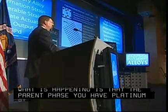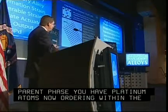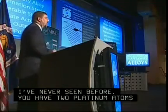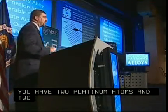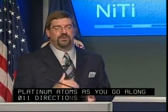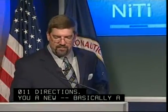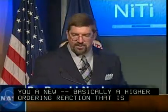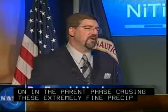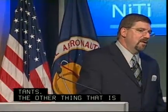doing it in a way that I've never seen before. You actually have 2 platinum atoms, then 2 nickel atoms, then 2 platinum atoms as you go along 011 directions in that particular plane. So you have basically a higher ordering reaction that's going on in the parent phase, causing these extremely fine precipitates. The other thing that's unique about these precipitates, if I could have the next slide, and